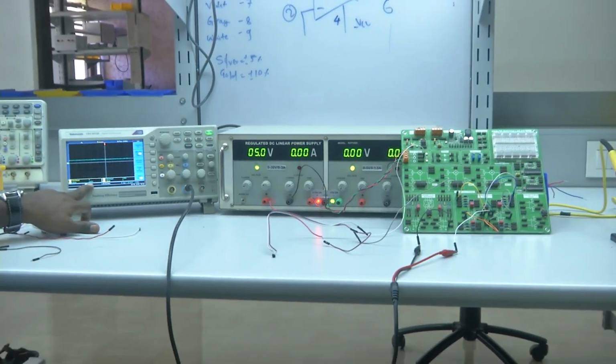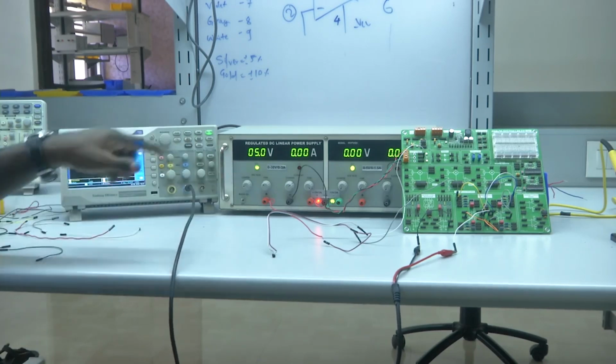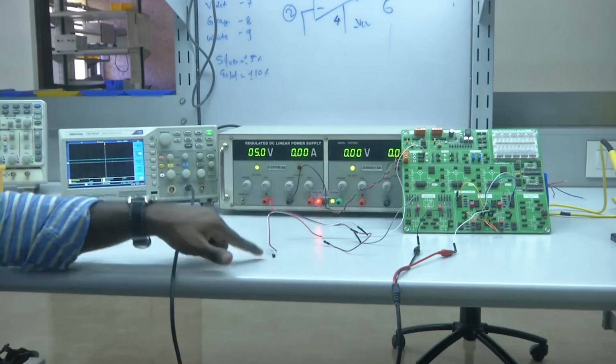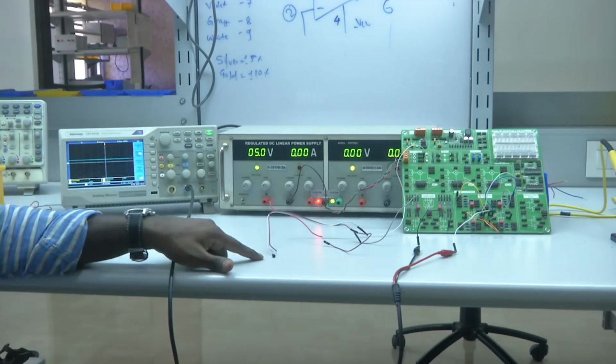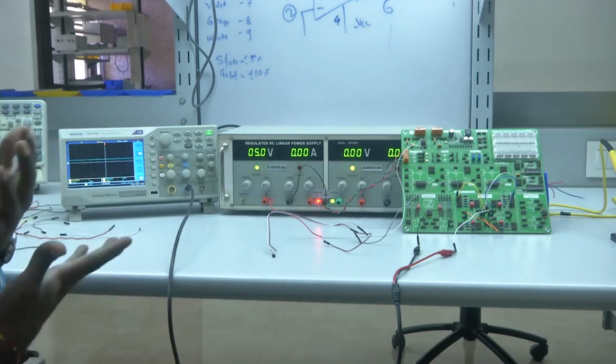How can we say? The reason is that when we look into the sensitivity of the temperature sensor, 10 millivolt per degree centigrade, 1 degree will always be represented with 10 millivolt. Since we have a gain of 10, 1 degree will be represented with 100 millivolts. But now I got 2.8 volt, which means that it corresponds to 28.1 degree centigrade, which is also the same as the room temperature.